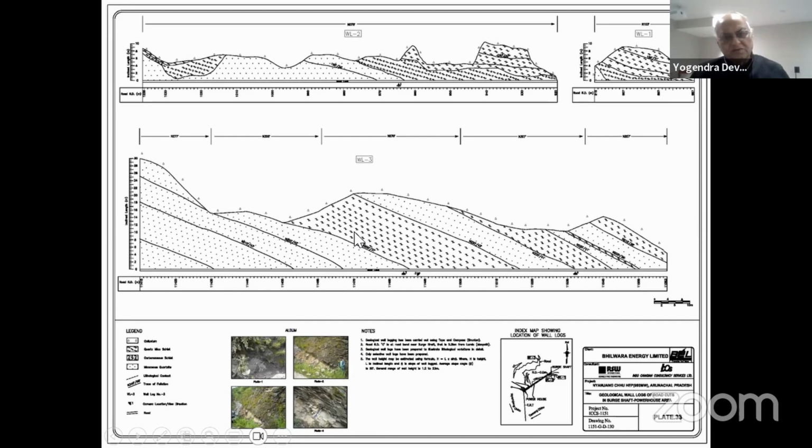So geological logs are basically prepared all along the road. If roads are available, you get very good information from that, or you can use it for projecting the spatial information which you are getting in a particular project area. And you can evaluate these things by photographs and whatever else you can give. The locations are shown in an index map.